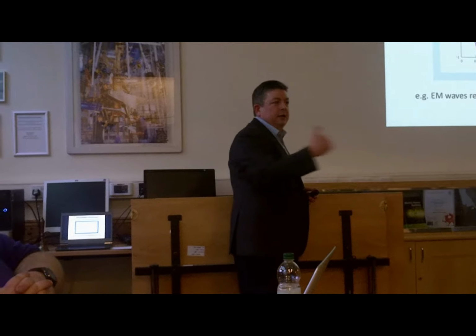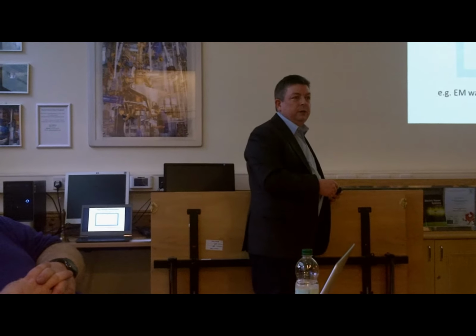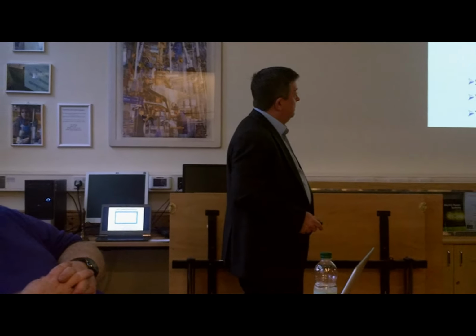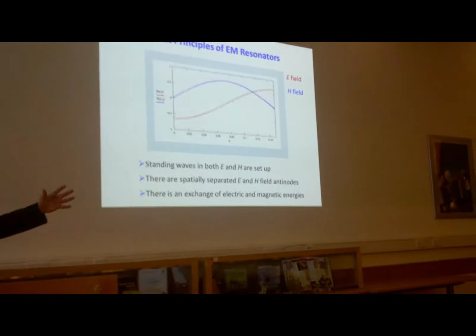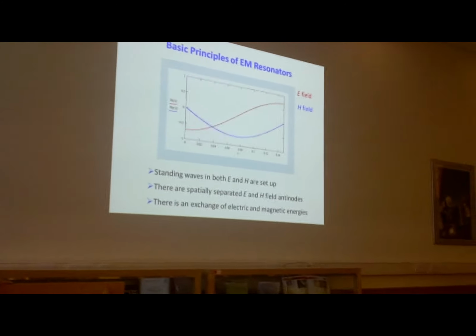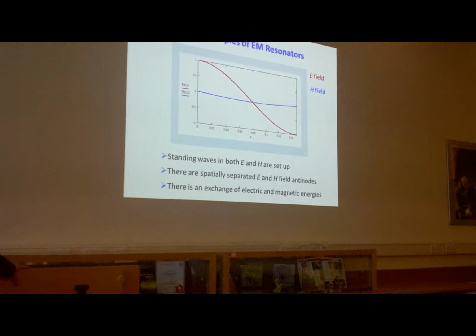A transmission line carries waves in one direction; with a discontinuity at the end, you get a standing wave, and you can design any resonator you want that way. You can have open circuit or short circuit boundary conditions at the ends. And this is a situation where you have an open circuit transmission line, where you set up microwaves along it, and that's the standing wave that you get as a result of this microwave resonance.